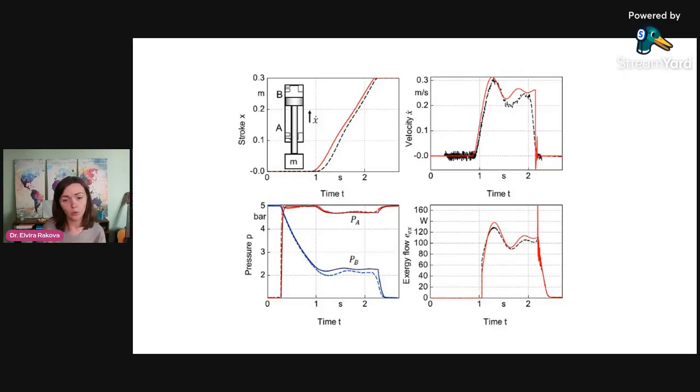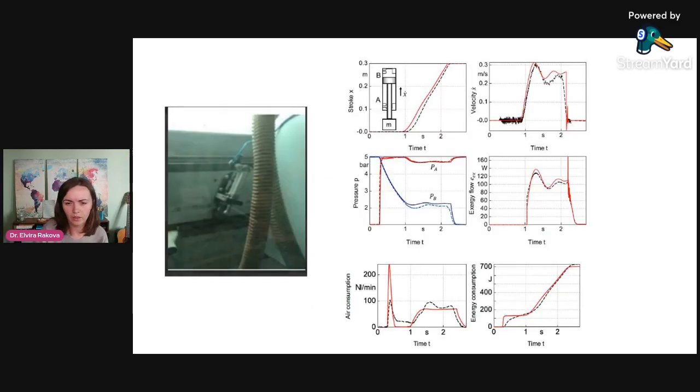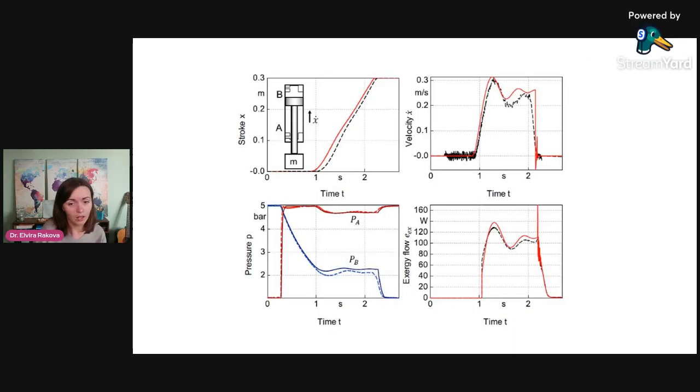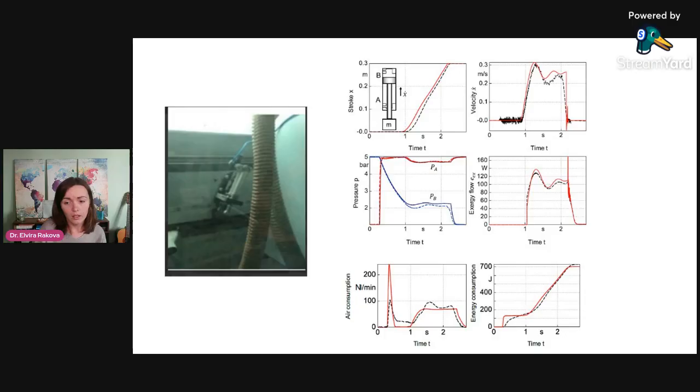So those kind of things where we have an end point of use. And what we have usually there, I don't have it here, but this is my cylinder, you see? And here is a long pipe that is then connected to the valve. In order to make this cylinder move, I need first to switch the valve into the position where the supply air now goes into the pipe, and then into the cylinder.